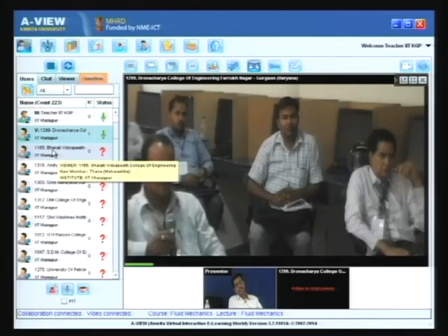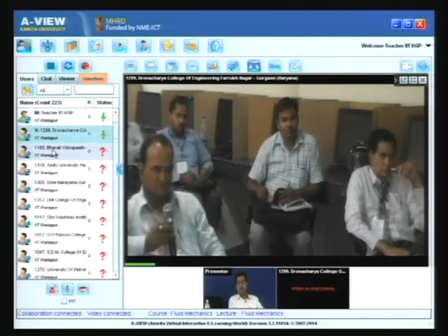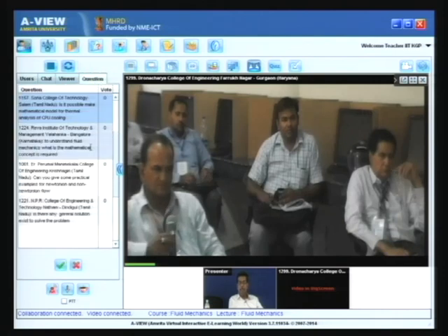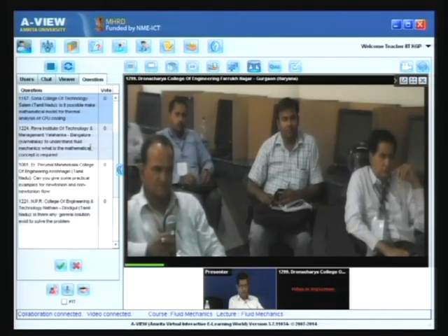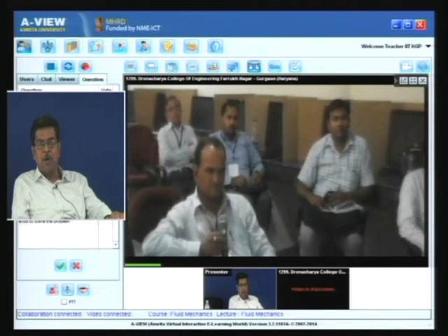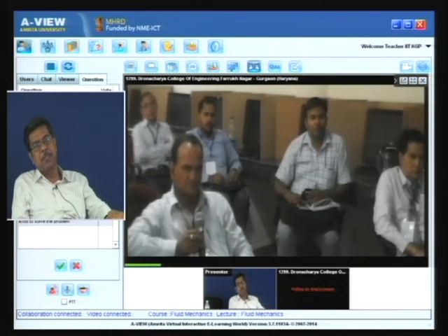But here, for simplicity, definitely we have considered that at the outlet of the rocket, the rate of discharge remains constant relative to the rocket. But if that changes, things will be complicated. This will be a picture at any instant. But I feel that when the rocket goes up, the relative velocity of the jet discharging from the propelling nozzle usually becomes constant with respect to the rocket.